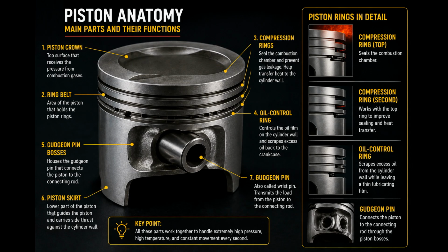But this creates another problem. That clearance can allow combustion gases to escape past the piston. It can also allow engine oil to enter the combustion chamber. This is where piston rings become critical. Now let's go to the piston rings.